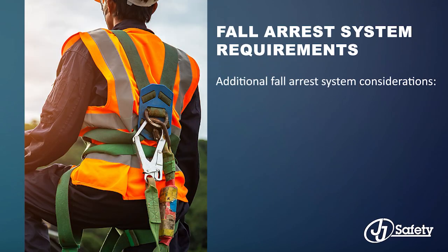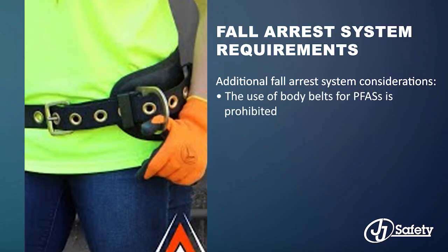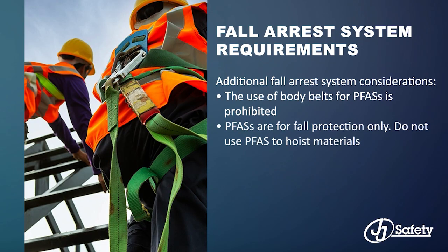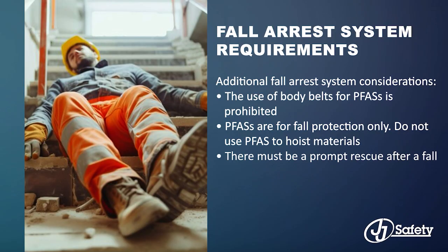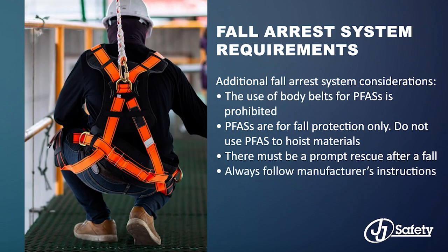When working with fall arrest systems, it's important to remember the use of body belts for PFAS is prohibited. PFASs are for fall protection only. Do not use PFAS to hoist materials. There must be a prompt rescue after a fall, and always follow the manufacturer's instructions.